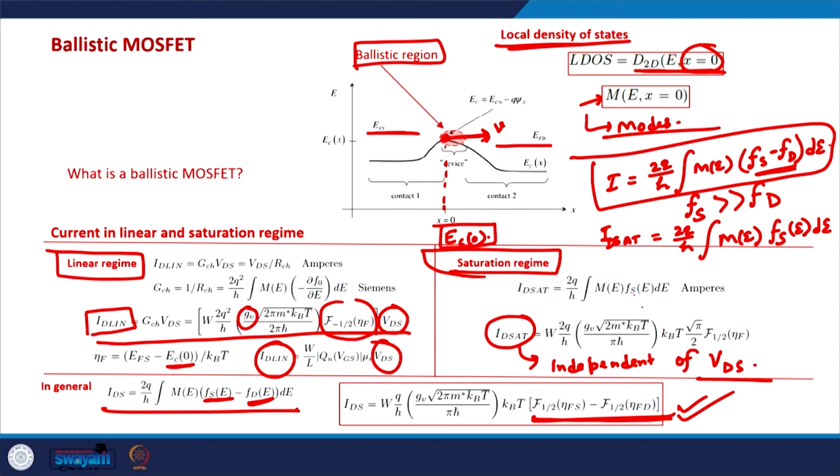I would again repeat it just to emphasize its importance, that the exact understanding of ballistic MOSFETs or modern MOSFETs is better done when we do the calculations self-consistently, when we take the semi-classical equation of transport and the Poisson equation of electrostatics, and solve them self-consistently.